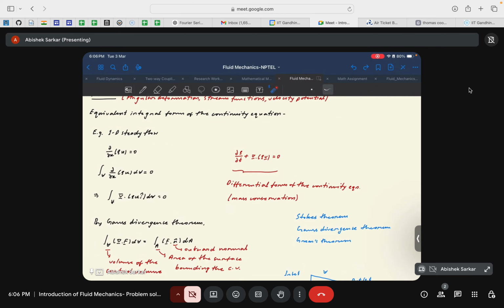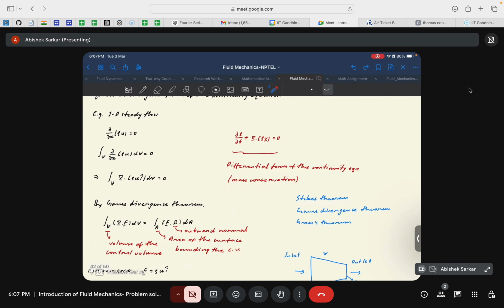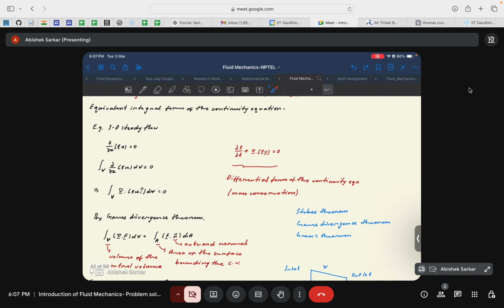But if you're going for finite volume methods, which are more commercially used in different kinds of commercial software such as ANSYS and OpenFOAM, which use these finite volume methods to solve the flow governing equations in the flow domain. By the name, finite volume scheme means they are integrating the equation over the entire grid element or the volume to solve these governing equations. So when integration gets involved, we are more or less aligned towards the integral form.